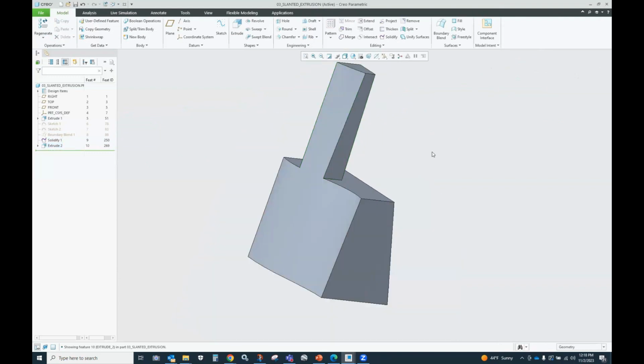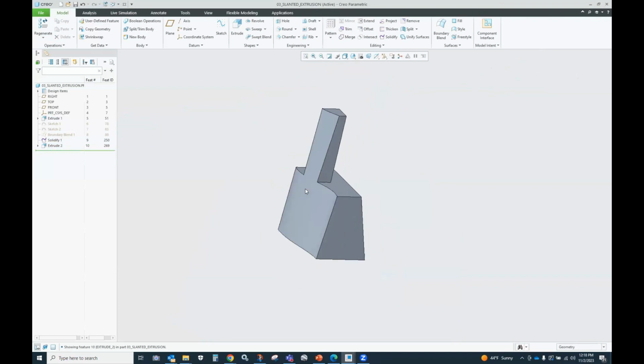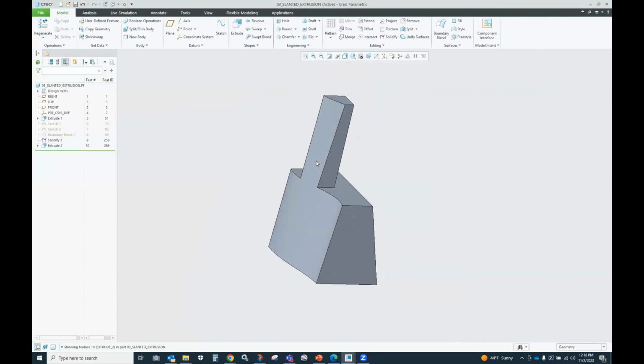So don't be afraid to try things like that. If you do work on consumer type products where you have more organic kind of geometry than anything else, try using those open cross sections. When in doubt, make it closed, right? When in doubt, make it closed. But if you can get away with fewer features to get where you want, you're always better off, right? Fewer features, fewer IDs, fewer references, more robust, right? Is that Papa John's slogan? Better ingredients, better pizza, right?